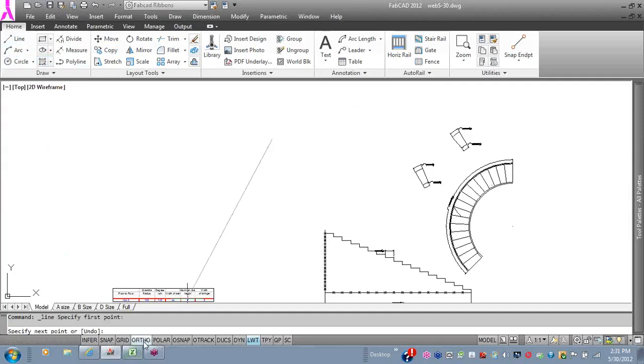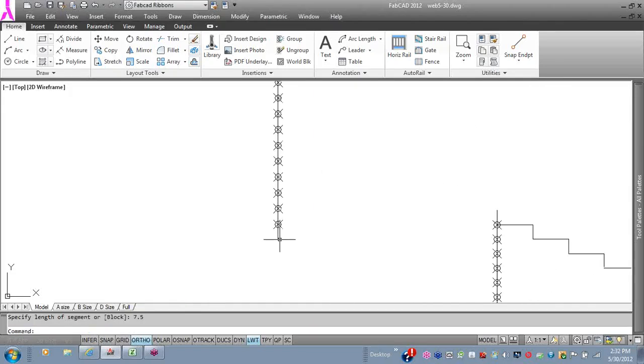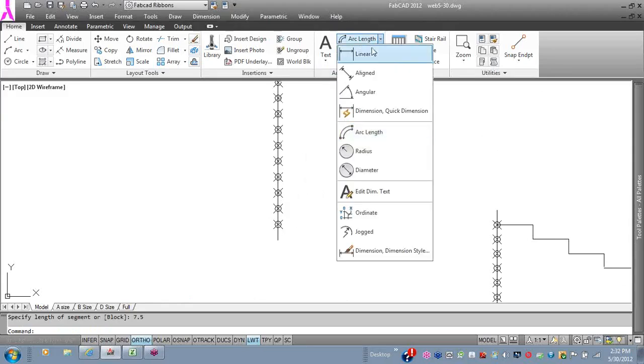I'll just draw another thing here, and something down here. The measure command is like a hatch thing. So with measure, you select the object to measure, and say your maximum riser height, you can get away with, say, 7.5 inches. I'll go 7.5. So what this does is that from the end of this point here to this node is 7.5 inches. I'll show you.